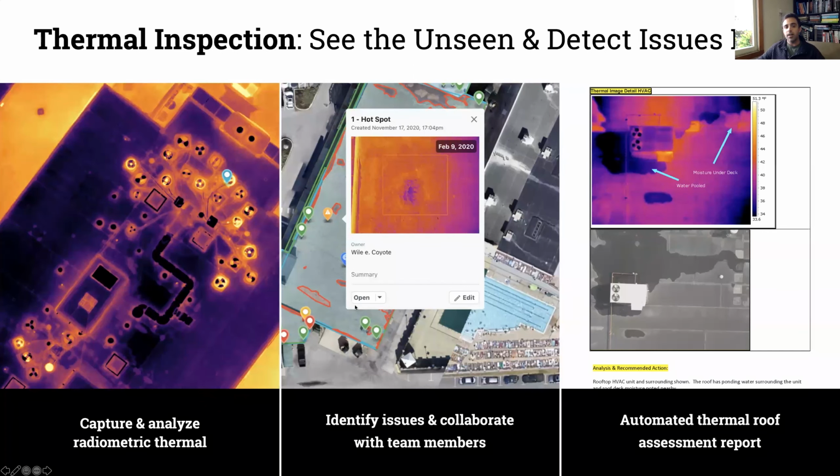The headline that we've heard from a lot of our roofing customers is we're detecting things with the thermal imagery that we would not detect if we were boots on the roof inspecting it. Obviously, the thermal allows you to see through the membrane and detect intrusions that might not come up to the surface. We fly all our thermal missions half an hour after sunset. And while AI generates the defect detection, we still have roofing engineers evaluating the imagery before it gets delivered to you. So it's two parts: one part AI, one part human engineering on the reporting.